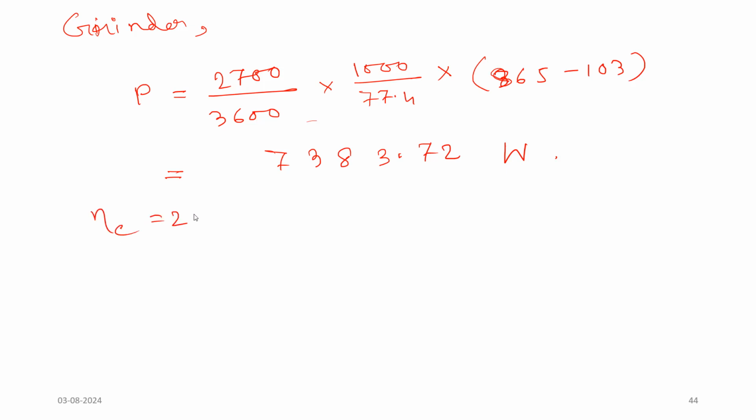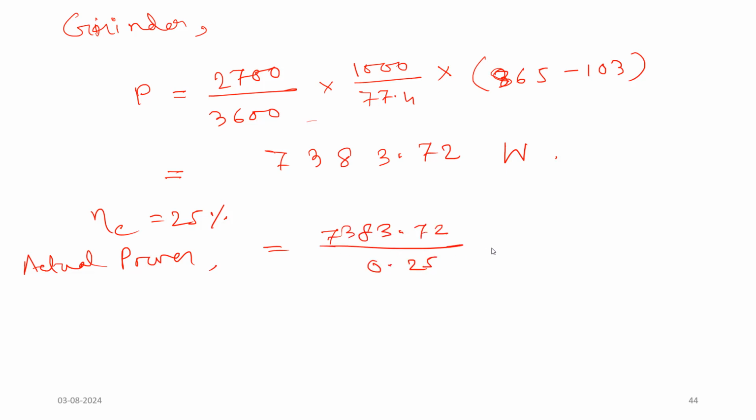So the actual power required is 7383.72 divided by 0.25, which is nothing but 29534.8 watt, that is 29.5 kilowatts.